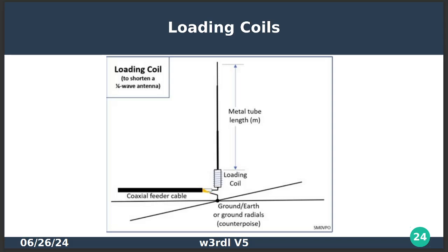That is an inductor, yes. So the way this particular one works, I mentioned the Wolf River coil. It's got a collar on it. It's got a coil here, and then it's got a collar on it. You slide the collar up and down the coil, and it makes contact with a certain point on the coil, and then there's a shorting wire. That changes the electrical length of the antenna so that you can tune it to whatever band you want.